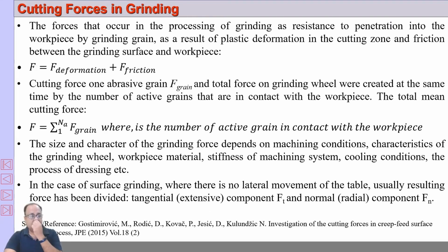The total cutting force is the summation of the force required for deforming the material and the force required to overcome the friction, because there is a wear flat, as you have seen earlier, so there will be a large amount of friction which has to be overcome by the grinding wheel. Therefore the force required is also large compared to conventional machining processes, and the total force is the summation of the individual forces encountered by each grain, summed from 1 to Na, where Na is the number of active grains. So we find out the average number of grains engaged with the workpiece at a particular point of time, and the force is basically a summation of all the forces acting on the active grains.